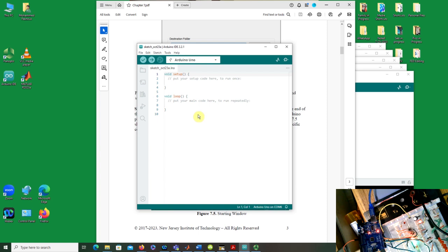And the reason is, for example, if I want to use pin 2 from the Arduino as an output, but then in my program it gets involved in so many other steps, right? So if I change the output pin to 5, then I would have to go through every step in the main program to change it. Whereas if I declare it as a constant through a variable name, then by just changing the value assigned to that variable name, it will change the entire program, right?